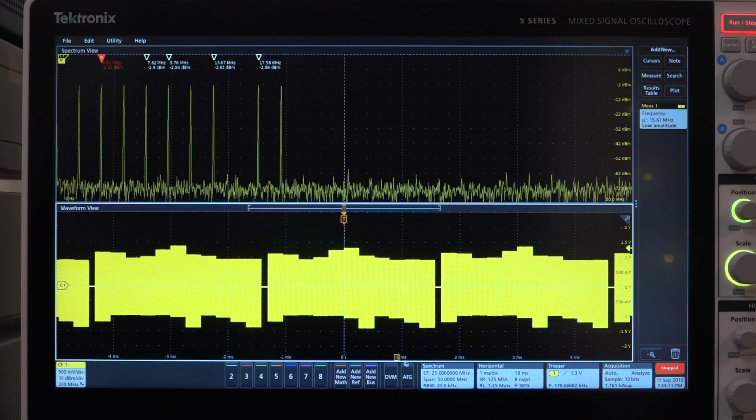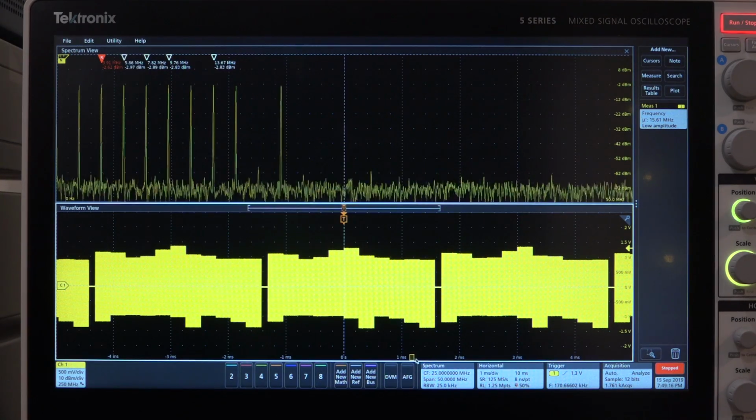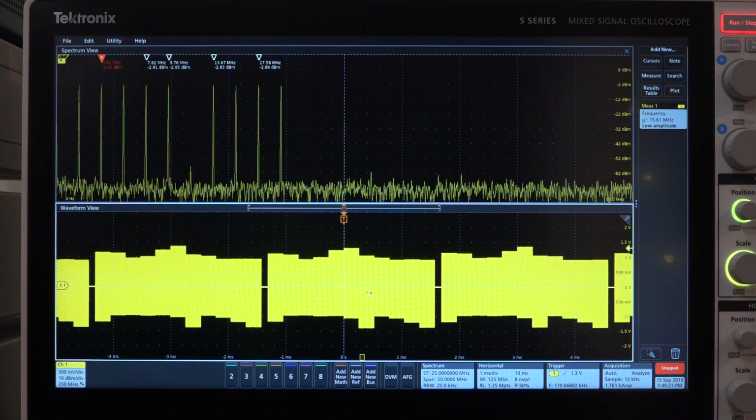And I can see this waveform would be really difficult to make without a computer if you were to do it manually. But of course here we did it very quickly using the instrument with the math interpreter. So for example, let's look at this section here. You can see we have roughly about 55 dBc of missing tone test rejection here, which is quite good with respect to the individual tones. With respect to the total power, it's even better than that, of course. So we have at least about 50 to 60 dB of rejection, or in worst case, I should say 55 dB of rejection. But this is from the unit itself, and of course the scope includes that as well.